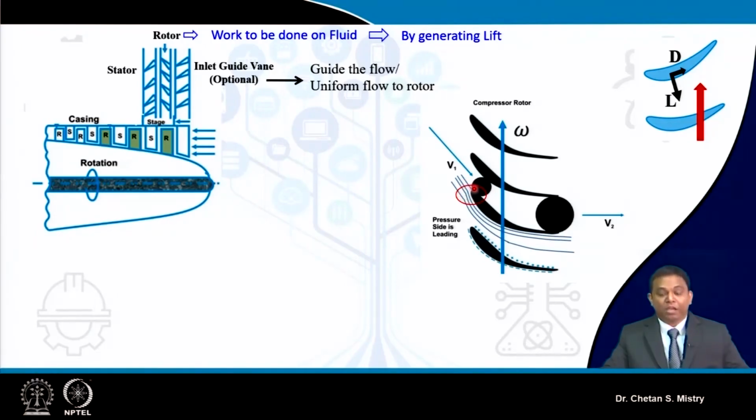But just realize, the shape of my aerofoil near the leading edge makes the area a converging passage, and that accelerates my flow. That means locally my pressure will be lower, and that is responsible for the suction of my air.